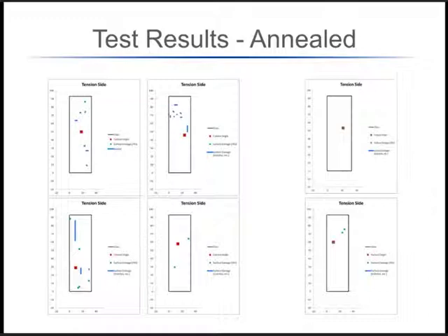drawings are what you can see on the right. You can see that red square with the green square in the middle of it. The rest of the samples ended up looking like the 4 that you see on the left, where the red square defines where the fracture origin is, and then you can see the other types of damage in there. The blue are typically scratches, and the green is some kind of a pit in the glass. So you can see that in the vast majority of cases, the fracture origin did not match up with where the damage was.